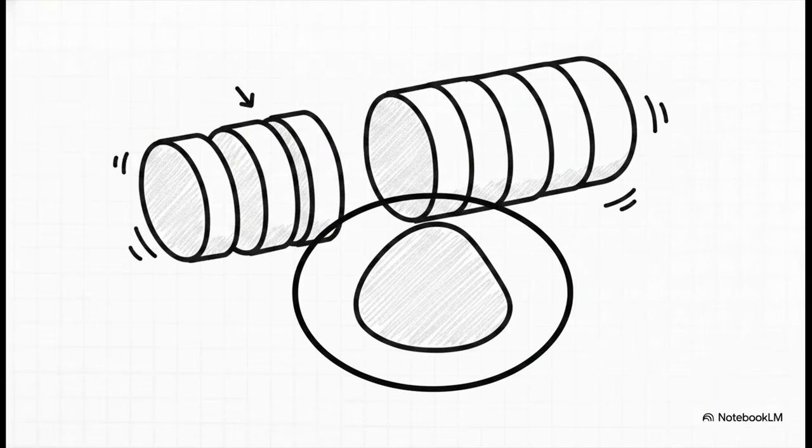Now, let's switch gears from flat geometry over to round parts, moving to the top right of our mental matrix. The rule for circularity, which is sometimes called roundness, is that each cross-section of a surface must independently lie between two concentric circles. Now, what's really interesting about this is that word, independently. Because we're in the 2D row of our matrix, we're evaluating the cylinder slice by slice, literally just like a loaf of bread. The standard dictates that this applies independently at any plane.